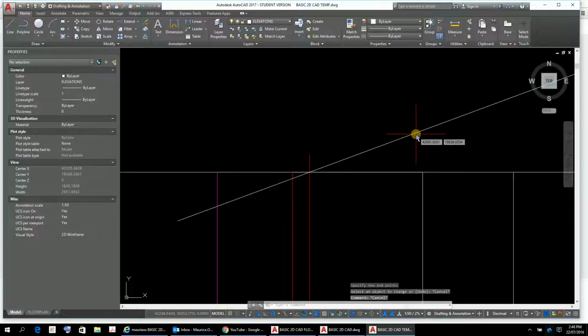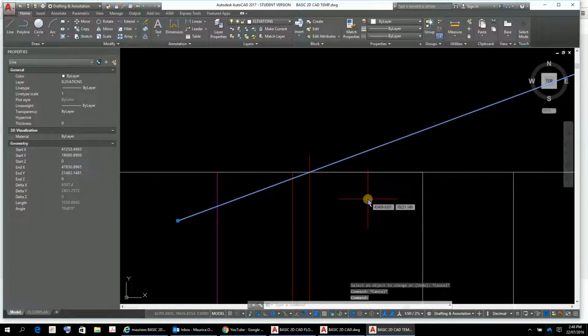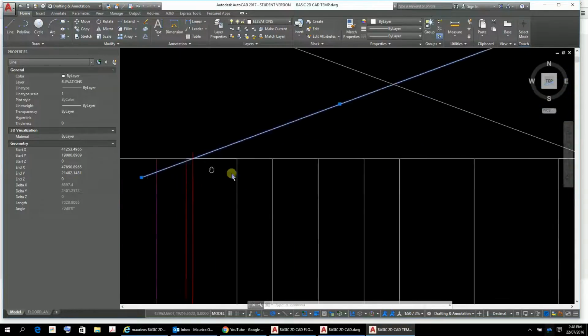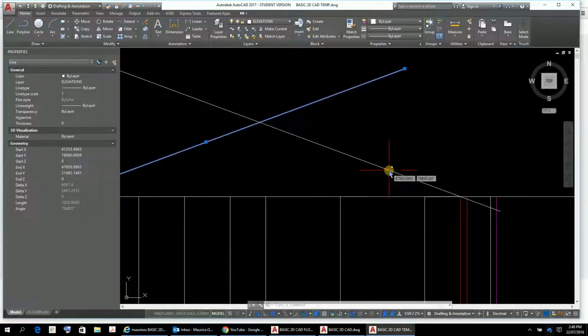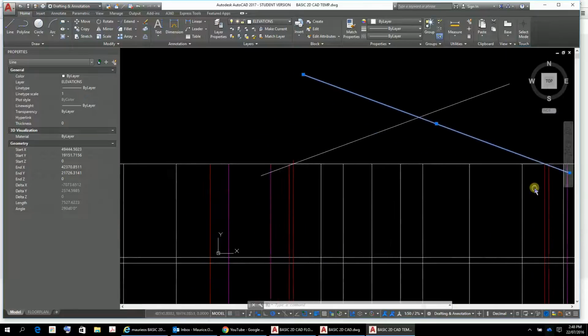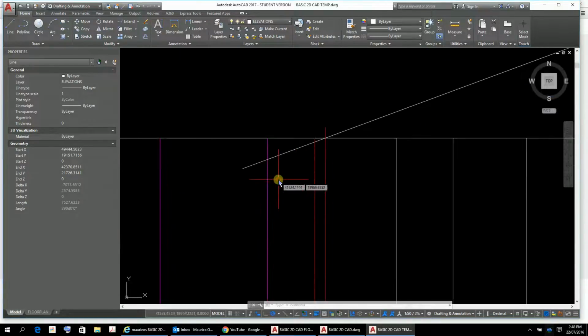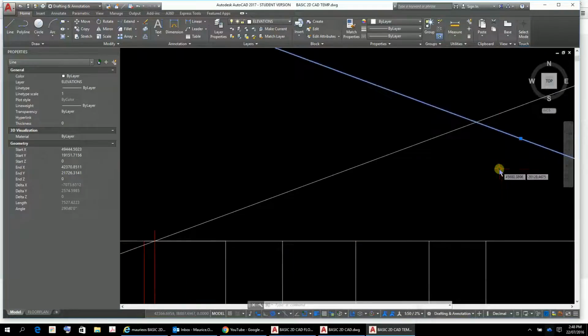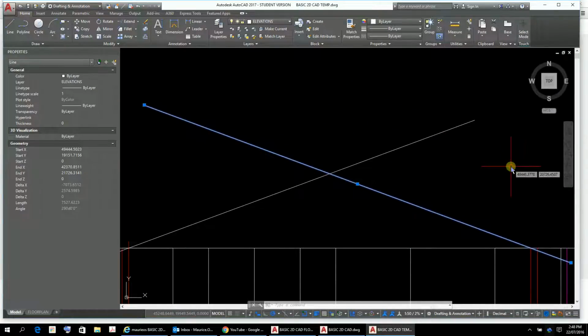Now let's just check this out. That's got a bearing of 70 degrees. Now bearings are measured clockwise from north, so 70 degrees to there, 20 to there would be 90. That seems okay. This one here, let's just do one click. This one here has got a bearing of 290, which is 270 plus 20, and that's through the frame line, and that's through the frame line out to the edge of our thing there, and they're intersecting there, which is going to give us the top of our truss